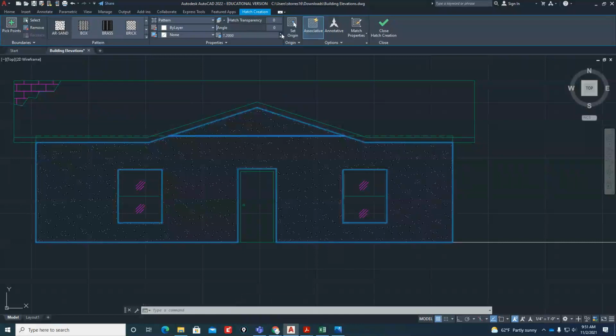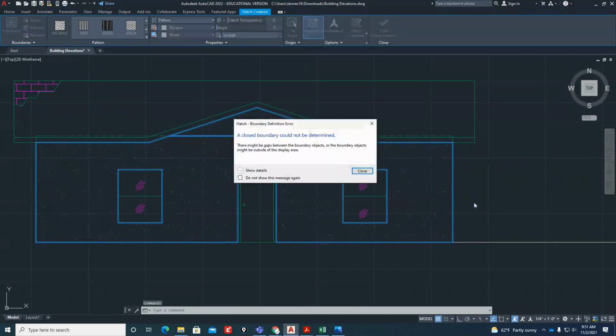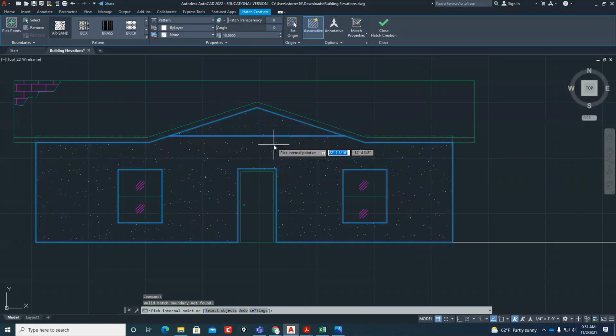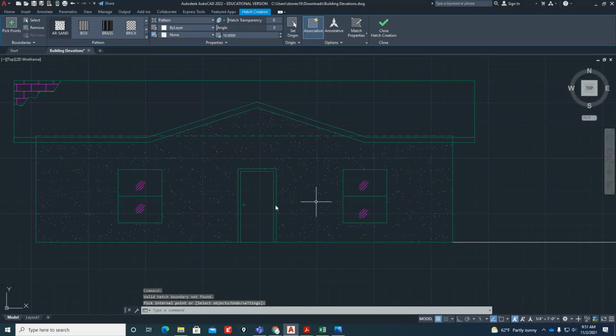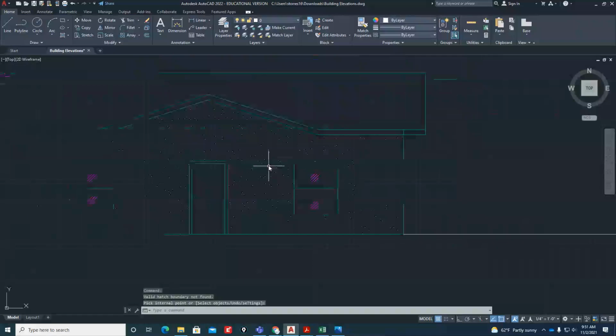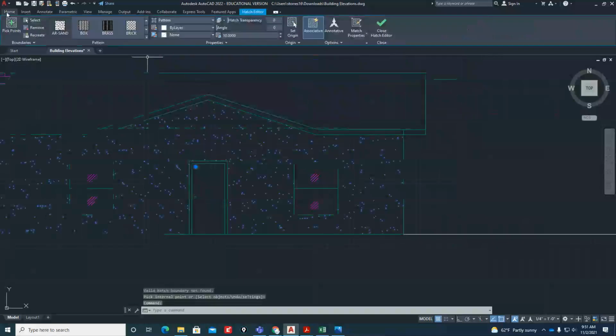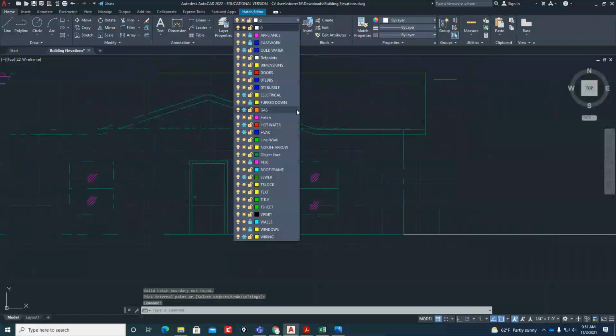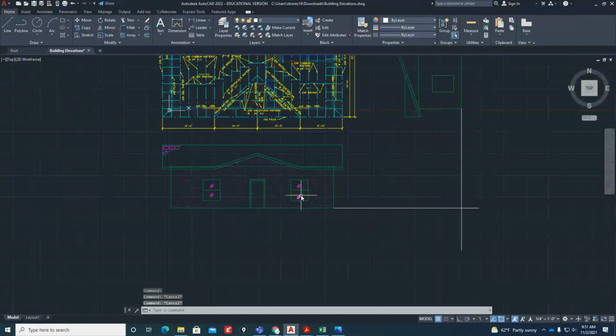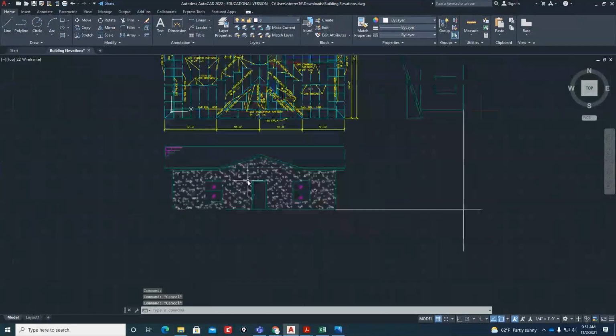We just need to show a couple of little dots in there. Maybe. A scale of 10 would actually work pretty nicely for your hatch pattern to represent stucco. We want that whole front, sides, and back to be all stucco. Just put it on the hatch layer. And that'll work. And then you can go ahead and label it.